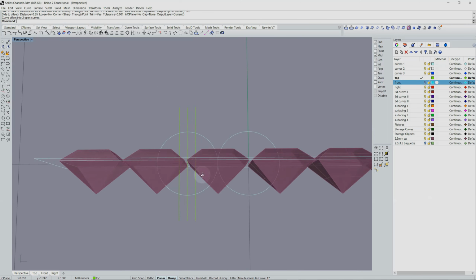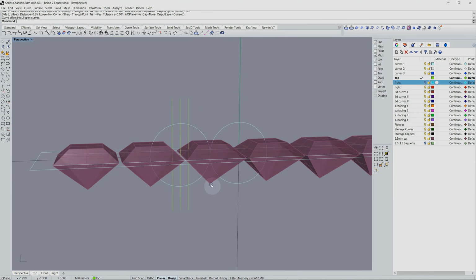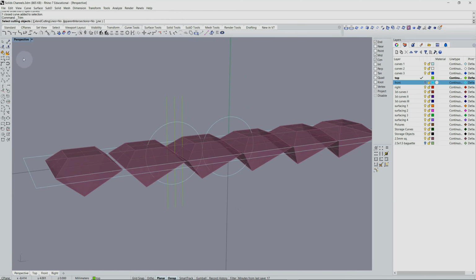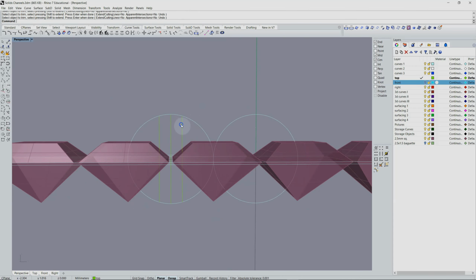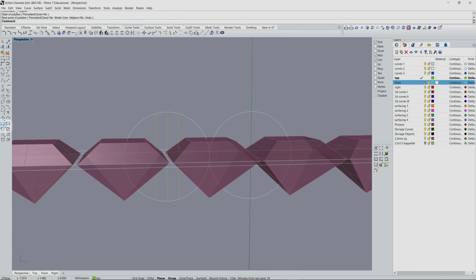I will then use the circle to trim my construction lines to equal lengths by choosing the Trim command off the side toolbar, choosing the circle as my cutting tool, and then choosing the 3 construction lines as my objects to trim. Using these construction lines to indicate the proper width, I will draw a rectangle by choosing the Rectangle Corner to Corner command from the sidebar of the Curves tab. Activating End Snap, I will draw the rectangle from the lower left-hand corner to the upper right.